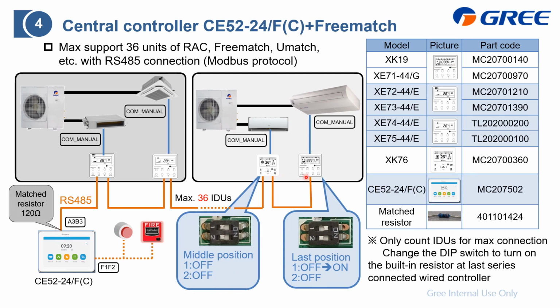And also, if the wired controller is located at the last, don't forget to turn on the built-in resistor to ensure the communication. Just follow these steps, then you can turn it on. If this wired controller is located in the middle, no need to change the dip switch. Just keep it default, that is okay.